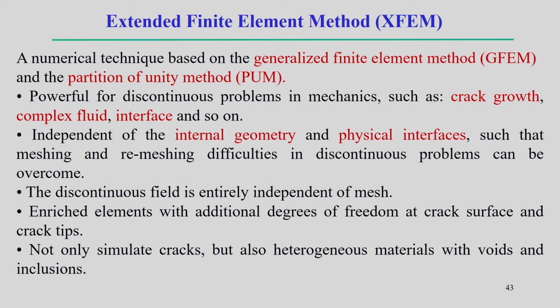So, the extended finite element method is basically a numerical technique based on the generalized finite element method, called GFEM, and the partition of unity method, PUM. In this case it is powerful for discontinuous problems. It is mostly associated with discontinuous problems in mechanics, such as crack growth, complex fluids and interfaces and so on. For all these kinds of problems we can use the extended finite element method.